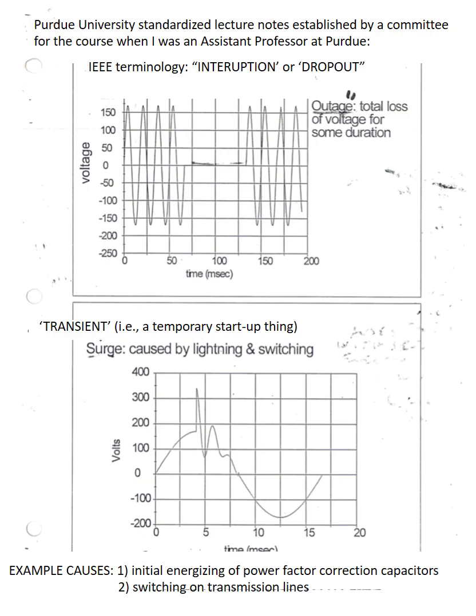So those are little blips that can happen and cause a surge, and a surge can blow out a circuit. In olden days, even static shocks would blow out your circuits. One reason for putting bipolar transistors around the rim of your chips and CMOS in the middle is the bipolar could handle the shock, where your pinouts are. That's not quite an issue anymore as much, but still, you don't want a huge surge coming in. That'll blow out even the most recent of chips.